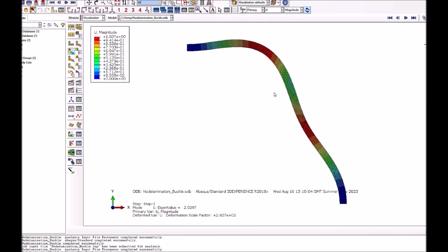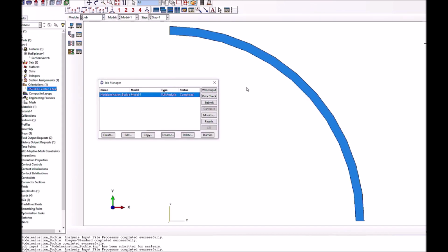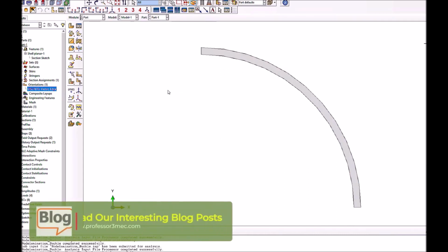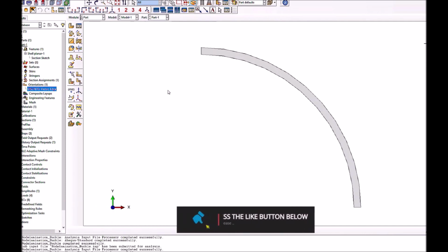So this is another very important parameter which you really have to keep an eye on when you are designing such kind of structures using composites. Okay, so now we have seen the effect of fiber orientation or orientation of the material, which changes everything. As you can see, implosion pressure or collapse pressure changes almost to double.